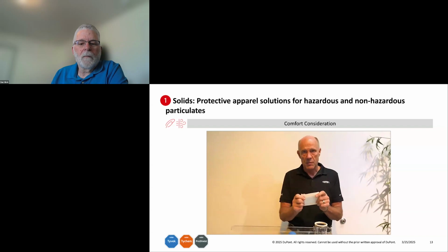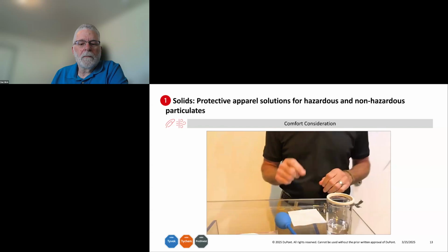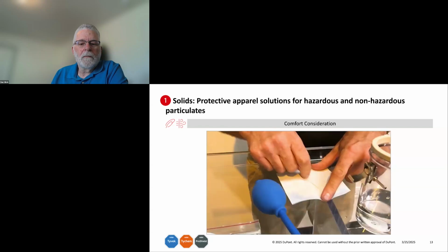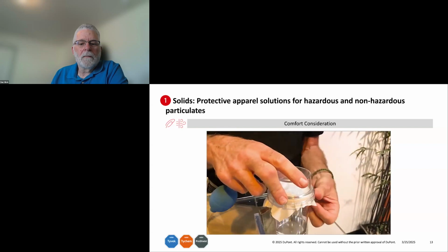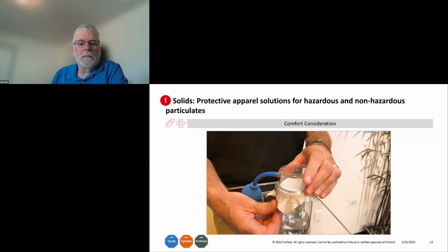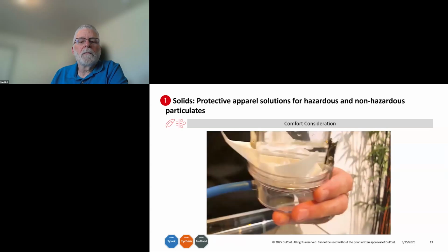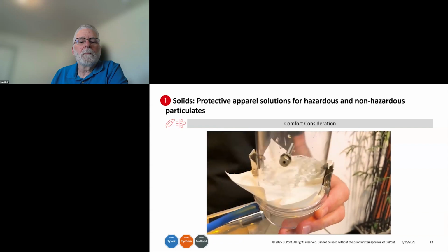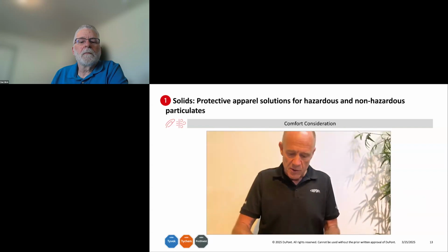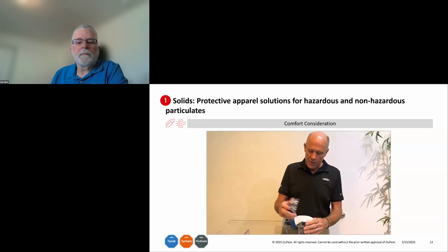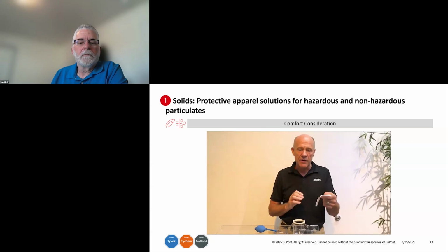One of the challenges with microporous film fabrics as PPE is that the protection that this fabric has comes from that very thin layer of plastic. So if I take my fingernail, which isn't particularly sharp, and I try and scratch the surface of that material, and now I repeat that exact same test, I turn it over, when I squeeze it, oh, now it's highly breathable. The reason it's breathing is I've compromised the protective layer that's on the surface of that material. And oh, by the way, over time, water will come through the bottom of it as well. So microporous film, not only is it not breathable, but the protection that you count on to keep your workers safe is a very, very thin layer of plastic, which is very easily damaged.